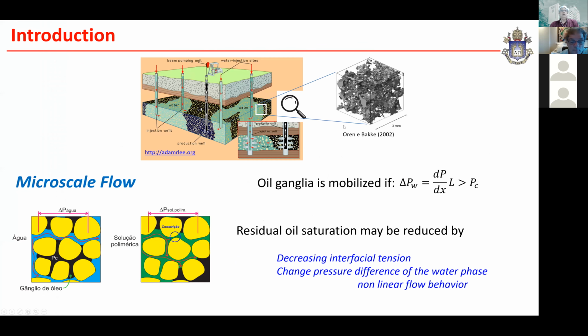Most of the applications I'm going to talk about here are related to oil recovery. Typically, when you're trying to recover oil from a reservoir, you need to displace it towards the producing well. The amount of oil that you're able to recover is going to be a function of how uniformly you're able to macroscopically displace the oil in the reservoir, but also how well you're able to displace the oil in the areas where the water has reached in the reservoir. And typically, even in the areas where the water has reached, there's still a lot of oil that gets trapped by capillarity in the pore space.